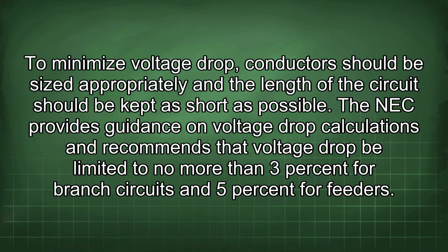The NEC provides guidance on voltage drop calculations and recommends that voltage drop be limited to no more than 3% for branch circuits and 5% for feeders.